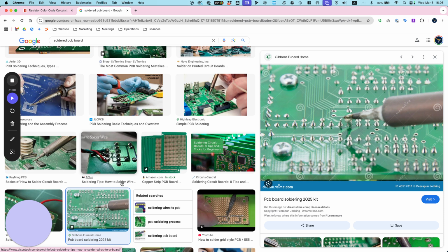But we have 4.2 volts per cell as our fully charged. What would that be? 12.6 volts. And then if 3.2 volts times 3 cells, what would that be? 9.6. 9.6 volts. Okay, so this is our range right here, 100% to, let's just say 0% if we were to give it a percent.